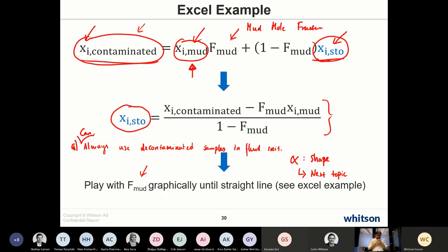But you might choose to not use PVT measurements on highly contaminated samples. And what you're going to say is, well, what's highly? Okay, well, it depends how much of this PVT data you have for samples that have no contamination. If you have a lot of that kind of data, I just basically wouldn't use the PVT data if it's 5% contamination or 50% contamination.